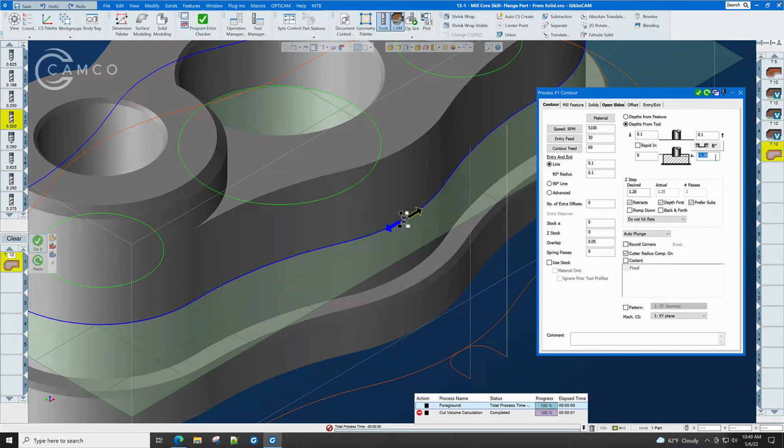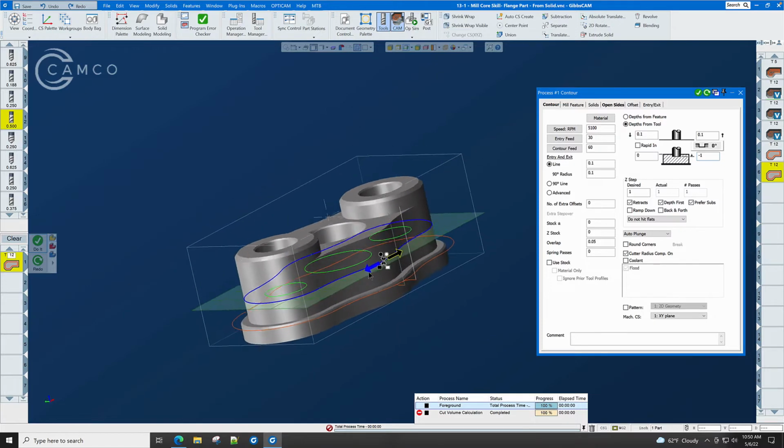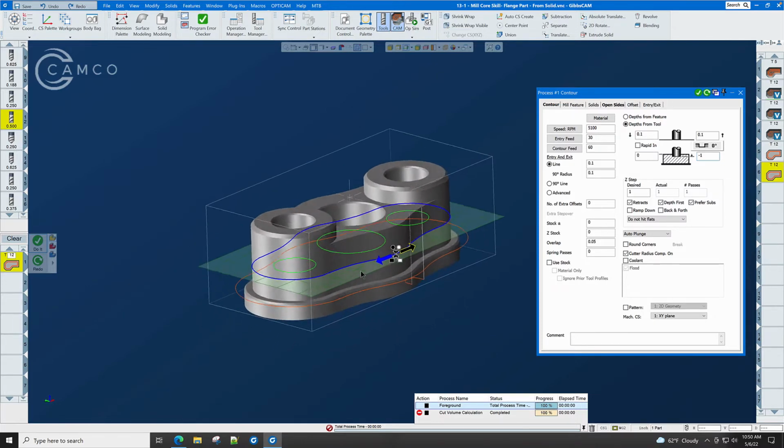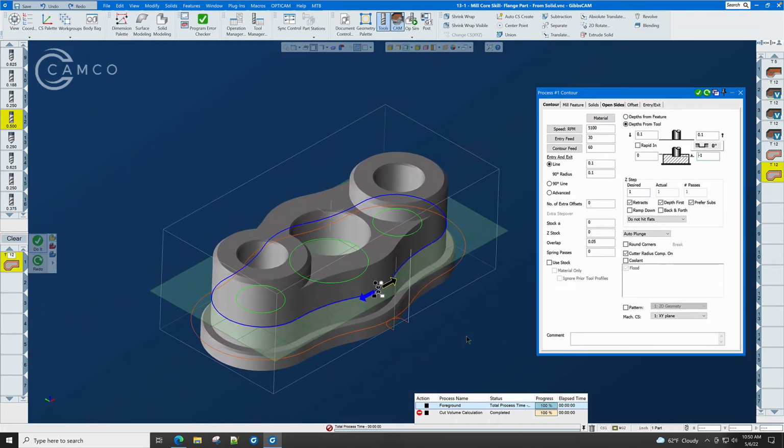Yes. Double click here in the bottom Z of the toolpath field, press your Alt key, and you can see that your interrogator cursor is now up. Click on the surface, and that surface has been added here into the bottom of this toolpath Z. When we press Do It, we get a toolpath. Notice that the toolpath is not affected by the height of the profiler. The profiler simply gets the geometry for us so that we can make the cuts.